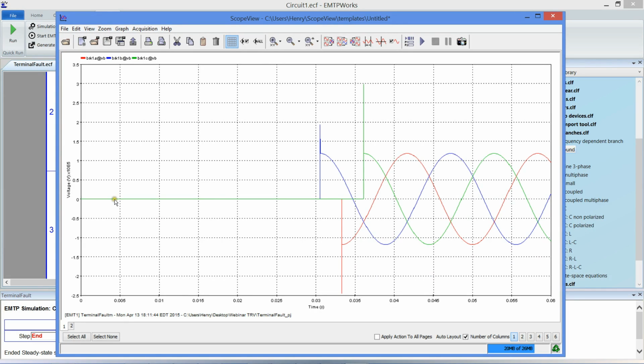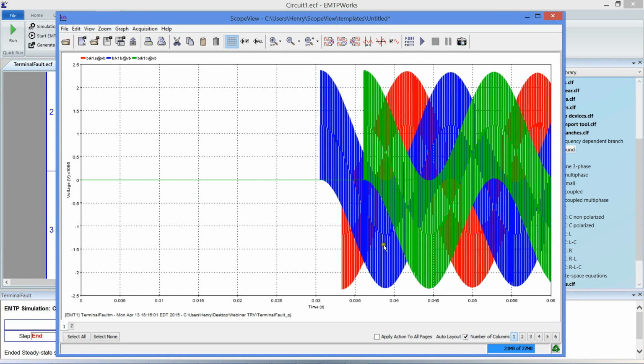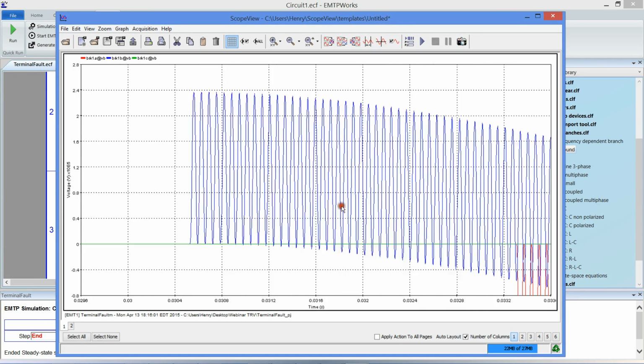Here we were cutting a current of an inductive transformer, which is really inductive. So we cut the current instantaneously. That's not very physical. That's why we have those spikes, and we don't find the oscillatory behavior the standard mentioned. But now, if I edit C, we can see this behavior. If I zoom on it, we have the oscillatory behavior, and it actually gives a very bad stress on the